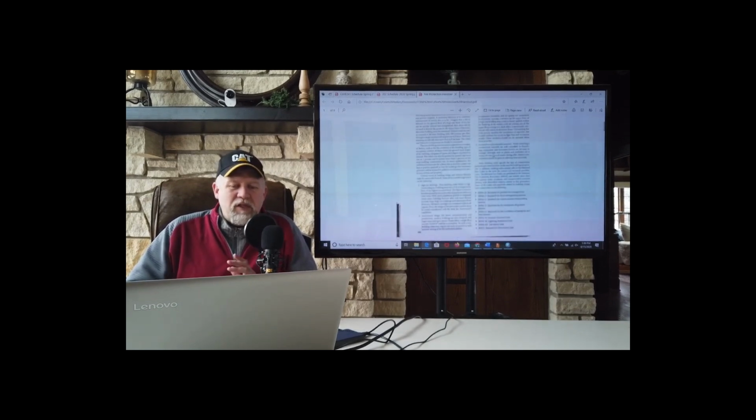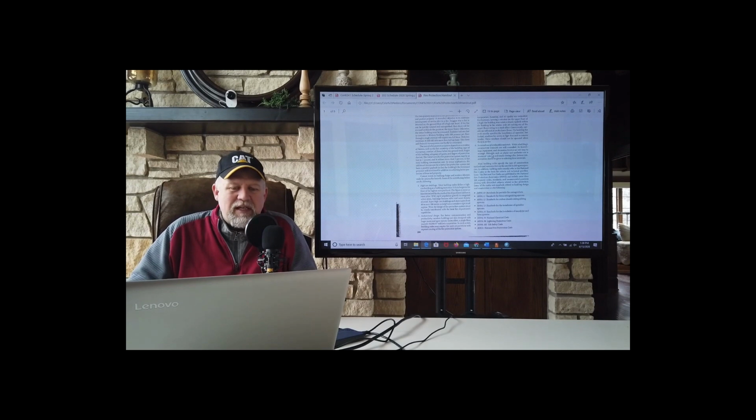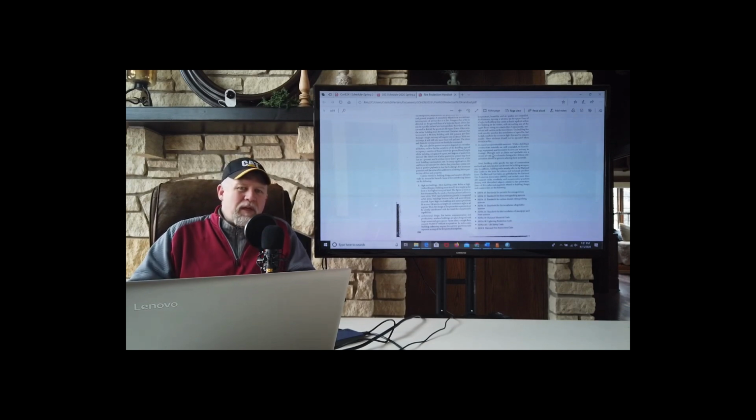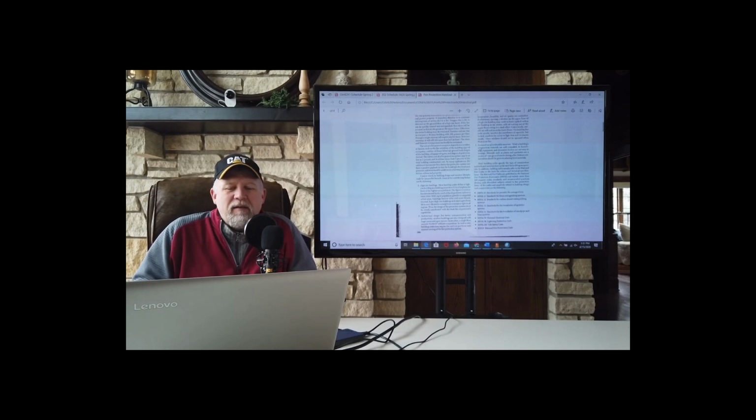You need to know here, just looking at page 266 there at the bottom left side of the page, things like what constitutes a high-rise building. The taller a building goes vertically, the more and more expensive it is going to become for the mechanical systems. Just know that. A high-rise is basically around 75 feet, but it's really defined by the local fire department and how high their ladders can reach.